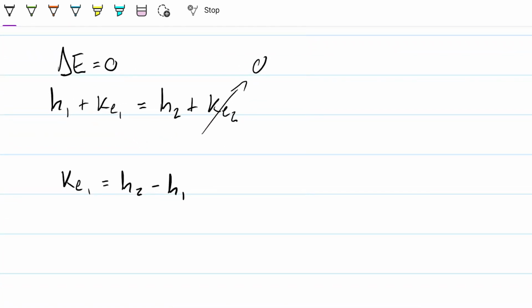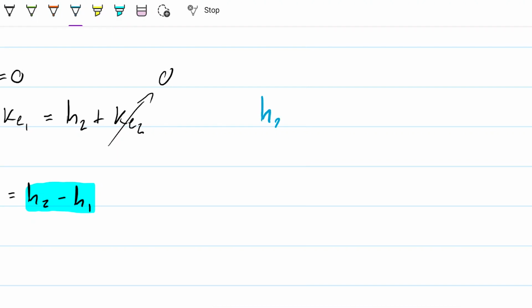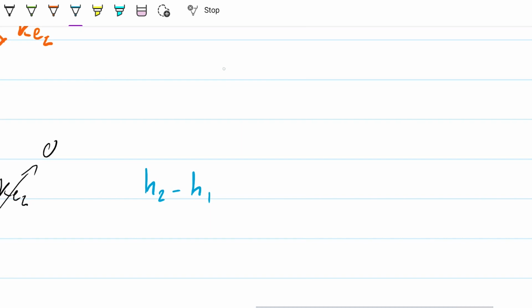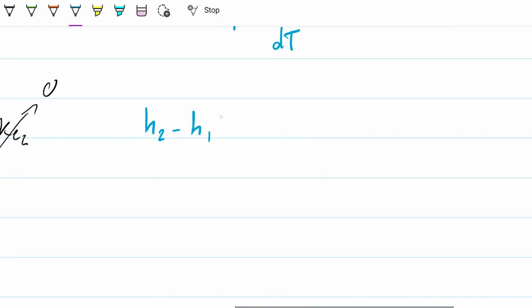Okay, so this difference here, if I don't have an ideal gas, I need to go look in steam tables, but if this is an ideal gas, what we can do is relate the C sub P, which is defined as dH/dT, as we've seen. So therefore, if I want this, I can just do Cp delta T. Okay, so C sub P delta T, C sub P for air is 1.005 kilojoules per kilogram per Kelvin. Delta T I happen to know because I calculated the other temperature. So this is easy peasy for me to grab.